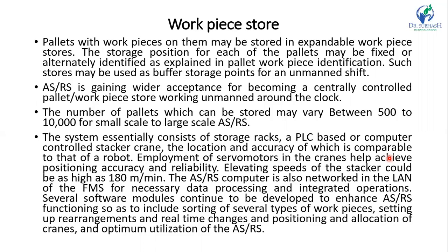So pallets with workpiece on them may be stored in expandable workpiece stores. So the storage position for each of the pallets may be fixed or alternatively identified as explained in pallet workpiece identification. So such stores may be used as buffer storage points for an unmanned shift. So workpiece storage and retrieval can also be automated in FMS.